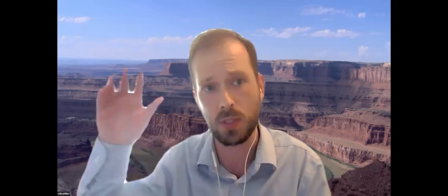So if there's some information where we can look at the landscape and say, we see that this is a channel that is ready to grade at an instant, a spot where it could shift its width quite large, or you can see the past impact of debris flows or landslides and say, right, this is a channel that is probably on that threshold of instability most of the time. Anything we can get out of that, we've been looking at in detail, though it's still in its infancy. We've spent a lot of time on the algorithms to extract that high resolution. In some cases, you can really see where landslides have come in, and it shifts that probability distribution and introduces a new lobe.